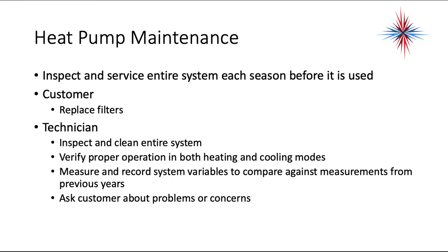For maintenance, relatively simple and similar to air conditioning maintenance. Inspect and service the entire system each season before it's used. The customer needs to know how to replace the filters, or there needs to be some filter change program in place. The technician should inspect and clean the entire system, verify proper operation in both heating and cooling modes, measure and record variables such as amperages, voltages, and pressures and temperatures to compare against measurements from previous years. Ask the customer about any problems or concerns. Customers live with the equipment. They can tell you about odd noises.